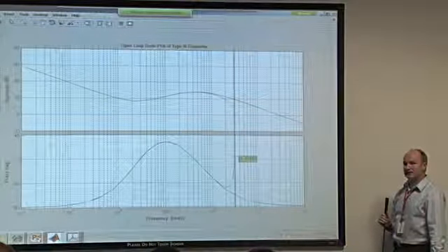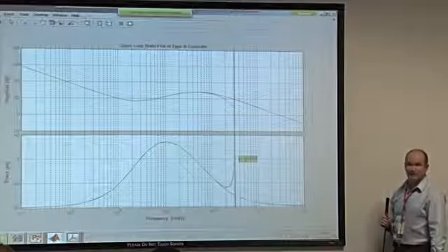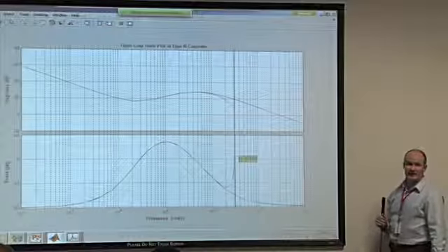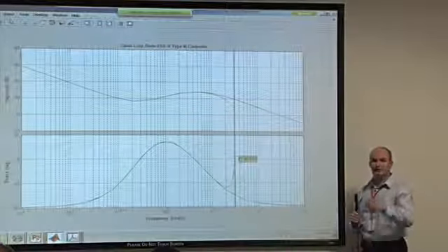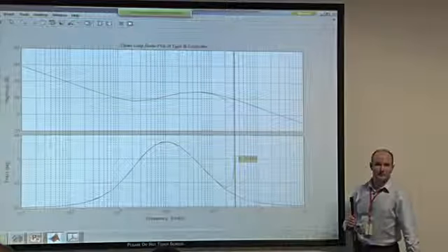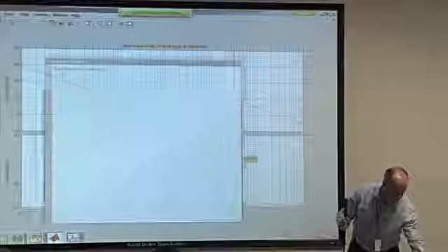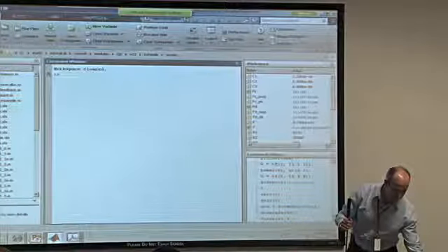But it doesn't take into account the phase lag which comes from the zero order hold. That you either have to account for manually using a minus omega T over 2, which is the phase lag we calculated, or you have to apply the zero order hold equivalent method, or the step invariant method, which is the same thing.